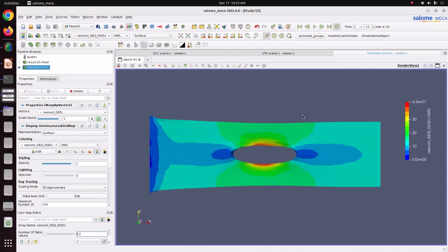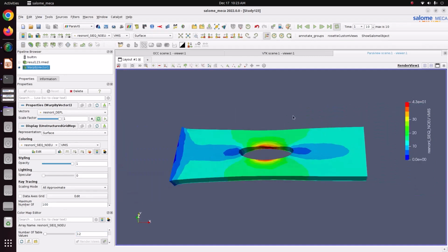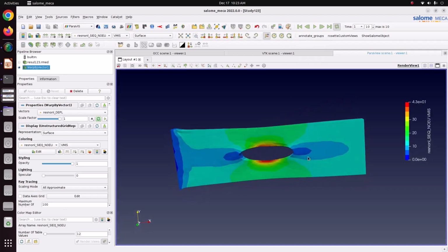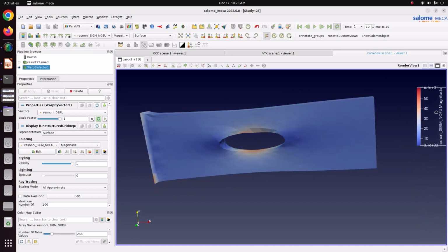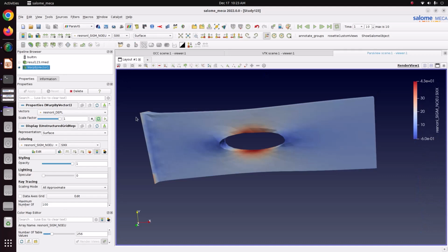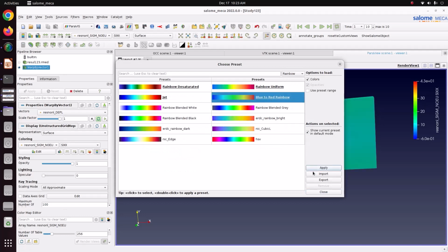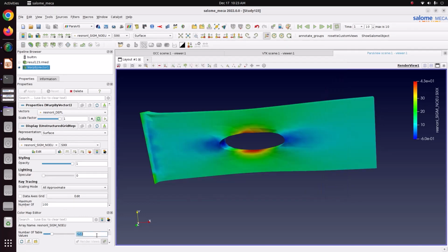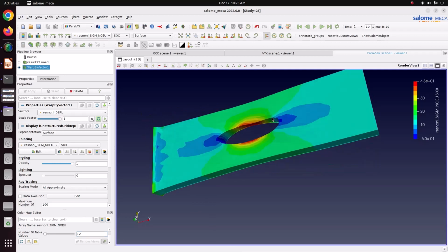The final one is this one. The maximum stress we are getting here, minimum stress we are getting here. We can change the background using this palette also, gradient background. Similarly, we can go for sigma. It's a directional stress. We can check with the sigma xx. We can change the color into blue to red rainbow. Just close it. This value make it 12. This also we can animate. Here I have given loop, that's why it's animating like this.